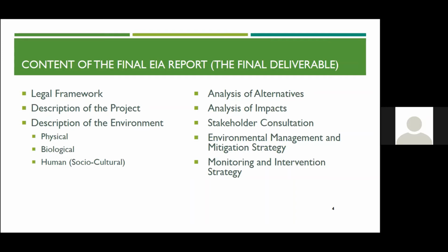Environmental management and mitigation strategy. This is based on significant impacts that will be identified earlier in the report, and an EMP or an environmental management plan will be created. Now, this EMP will address the mitigation measures for each significant impact, as well as it will detail the responsible parties for taking the action, as well as timing and equipment.